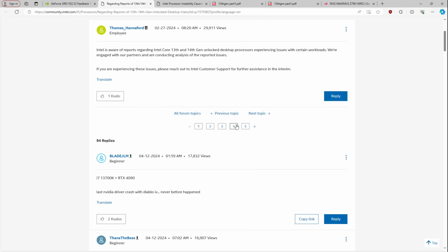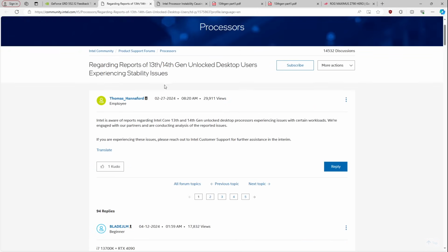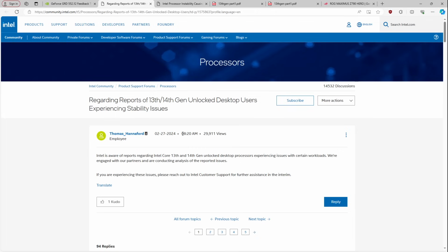Because each 14900K ships with a different VID table, and some of them are really bad. I imagine those are the chips that are failing all of these scenarios. You get a 14900K that's in the bottom 10% of the production run, and it just doesn't work at high load, because the VID table just isn't stable at 100 degrees Celsius.